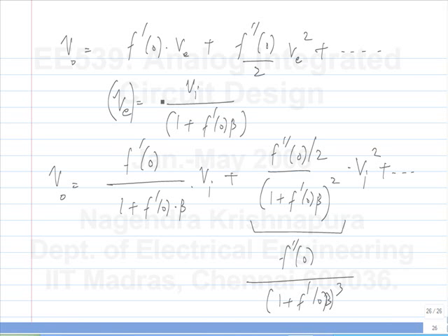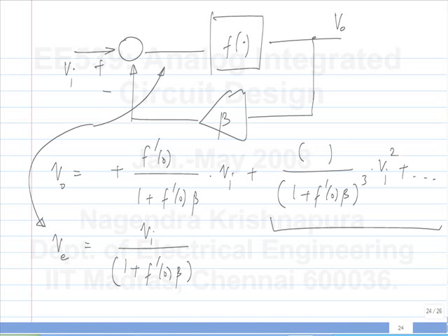No, it is true that it is because of neglecting terms I will get this, because the one is exact analysis, the other one looked like it was going intuitively in the right direction, but then it didn't go all the way or something happened. So, you figure out what that is, okay? In fact, you can simulate it and see exactly. You can put a sine wave, you assume some f, it doesn't matter. In fact, you can assume f so that all these other extra terms are small, okay? But then you look at the waveforms here and there and see what happens. So it is true. It is because of neglecting other nonlinear terms. There is no question. But you look at the distortion components and see why it behaves like that.